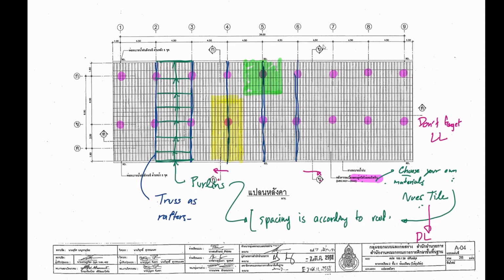So is there any case that water will go to the construction, or water ponding that you mentioned? Well, generally, if you use the slope recommended by the tile manufacturers, ponding should not occur. Ponding is like you have a pond on the roof, so to speak.